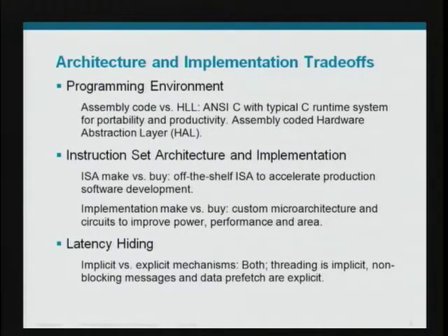Through the architecture, there were a number of trade-offs we had. We have a number of internal network processors. Cisco's probably used every startup, or at least evaluated every startup. We have a lot of experience with assembly code. We have models. We also have experience with the instruction memory and so on. So we came away with a number of points before we even started the architecture: we wanted to have a high-level language. Along with that, we didn't want to worry about slotted memory accesses or having to count those kinds of cycles. From an ISA standpoint, we wanted to have high quality compiler support.